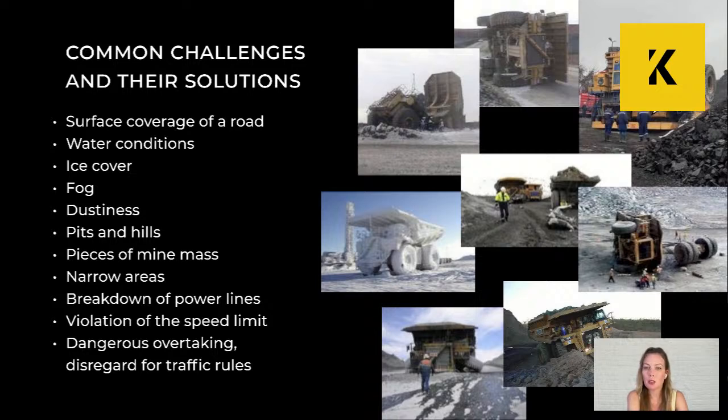Potholes and humps are a common issue if the quality of the road surface component is not up to par. They need to be addressed promptly using specialized equipment. For humps, they should be cut off with a bulldozer. For potholes, they should be filled with small crushed stone or gravel.